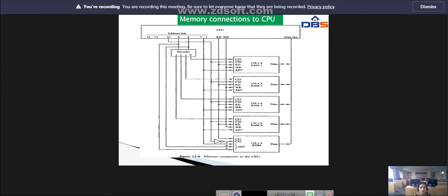Unlike RAM, programmable read-only memory retains its content when the computer is turned off. The difference between PROM and ROM is that PROM is manufactured as blank memory, whereas ROM is programmed during the manufacturing process. To write data onto the PROM chip, you need a special device called a PROM programmer or PROM burner. The process of programming a PROM is sometimes called burning.